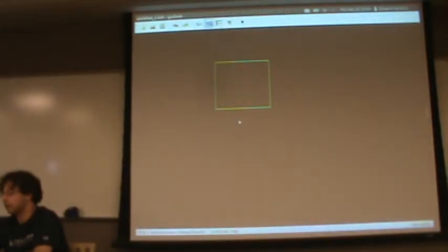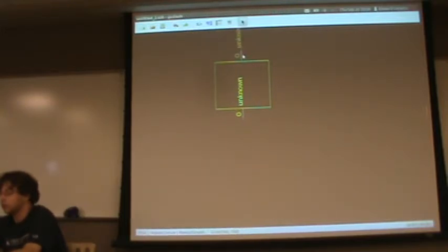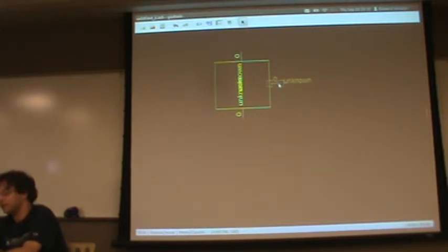So I'm just going to draw in those pins. So I'm going to add pin. Pins have 2 ends. Pins should always be 3 blocks long if you've got 100 as your grid size. The red end goes out, the white end goes in. The red end is what you're actually going to connect stuff to. So I'm going to drop in my 3 pins. I'm just going to rotate this one. I keep putting these backwards. Okay, 1 pin, 2 pins, 3 pins.